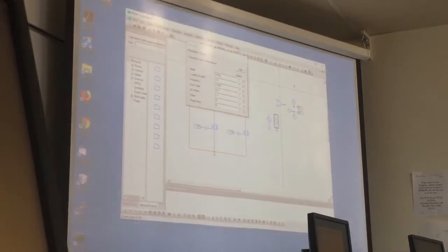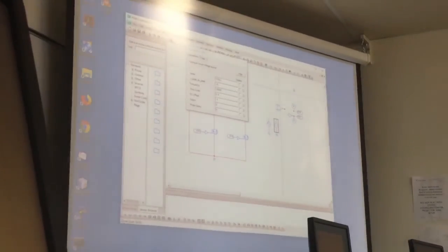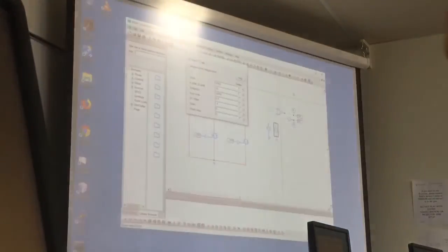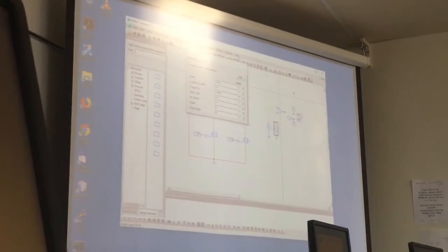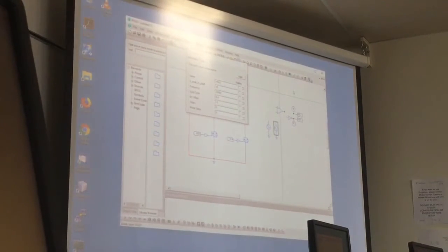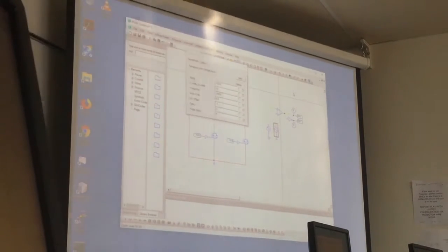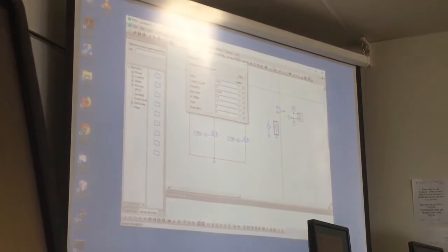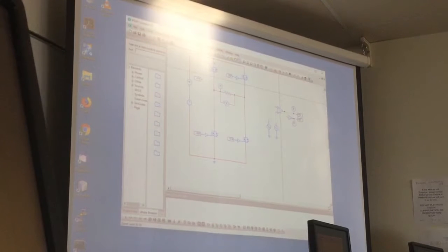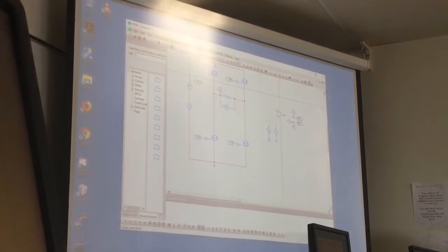You guys have questions here? Oh, yes, I was looking for that. Another thing, if you see, I don't have these black dots in my simulation, see? So something is wrong. For example, if you see here, you had 2 DC sources at the same point. I don't know why. See, here it's the same. For example, see my simulation? I knew that something is wrong. See, I don't have these black dots. I have them just when I have 2 wires connecting to each other.